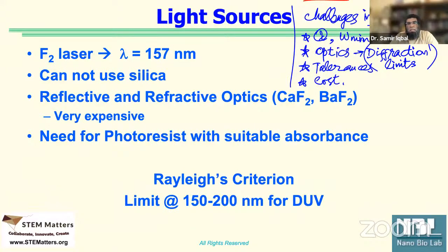There are a couple of tricks used in optical lithography, such as immersion lithography, where instead of using vacuum or air, we use liquids to change the index of the medium. Or there are techniques where we play with the feature size, so we add some extra areas. We skipped on that; the goal was to get into next generation lithography.